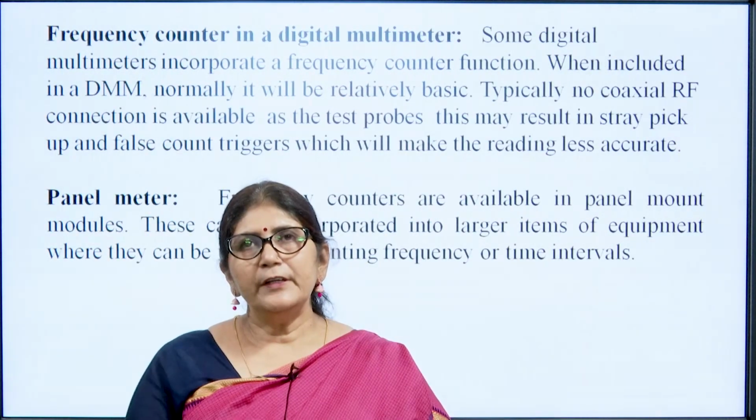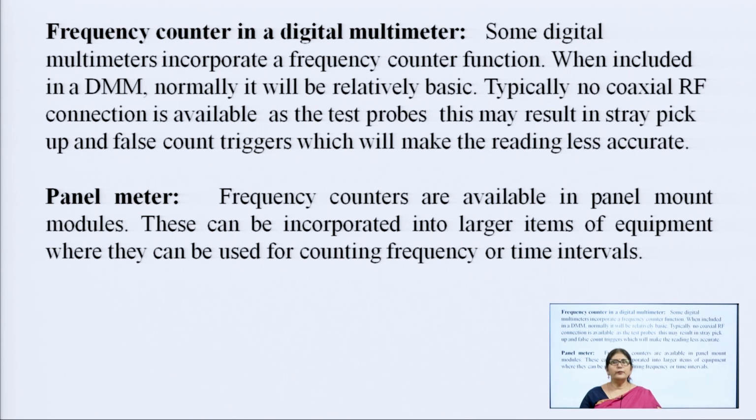Then the frequency counter in a digital multimeter. Most digital meters also have a facility for measuring frequency, although they are not very accurate measurements, but yes, we can measure the frequency using digital multimeters. In a digital multimeter, no coaxial RF connection is available as the test probe, so it may have false count triggering and other issues. So, not very accurate, but we can measure the frequency.